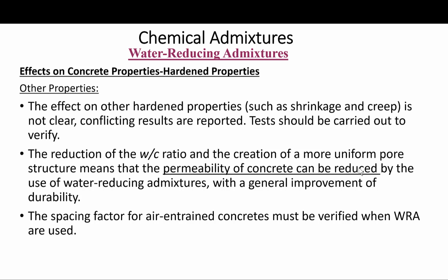With creep, the situation is less clear, and different admixtures may increase or decrease creep. So if drying shrinkage or creep values are critical, then tests should be carried out to assess the effects and design the concrete to reduce the values if necessary. This is a more complex issue, but you need to know about it.